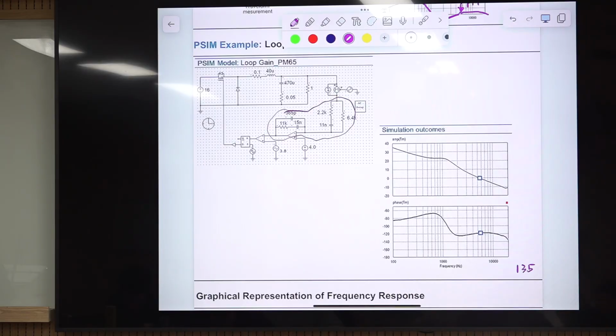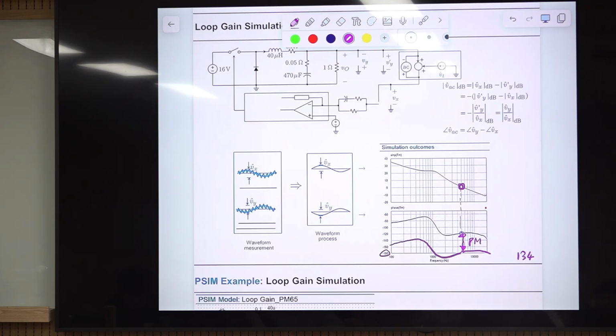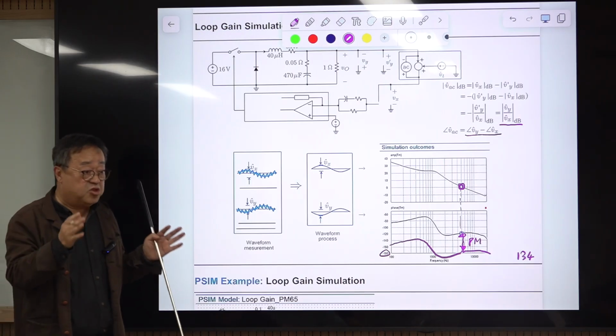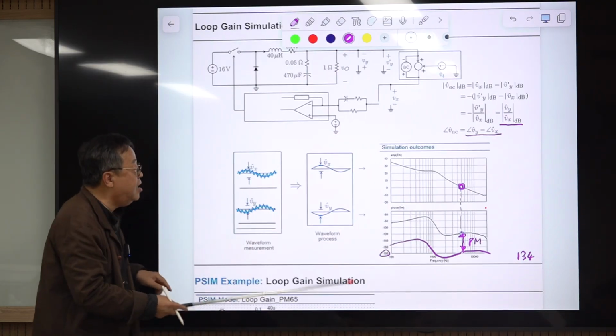I intended to specify the phase margin here, like this. Same plot. It really doesn't matter. Let me explain this. What I have drawn here is what? So we went through this, right? This is the magnitude of loop gain, which is very close to the true loop gain, and this is the phase of loop gain with the additional minus 1. There is some error because of the position of these two signals. So you should add minus 180 degrees, then you will get this.